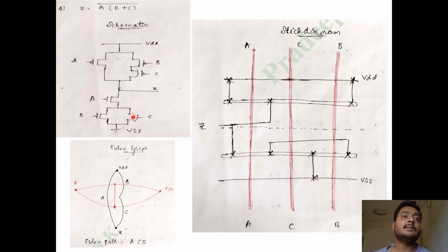So in this case, A, B and C is there. All three single terminals of A, B and C are joined together. So in these situations, you will find either AB together or AC together or BC together. So two at a time will always be available. You can see which one is available. BC is there, but I already used it. So the only thing available is AC. AC is already joined together, so it's available to me. What I should do is, whatever AC is there, I should take one terminal of B and join with them. That's it, right? So one terminal of B should come and join here. You short them, short to A and C. That means this intermediate connection is over. Okay, right. So this is how you draw the stick diagram.